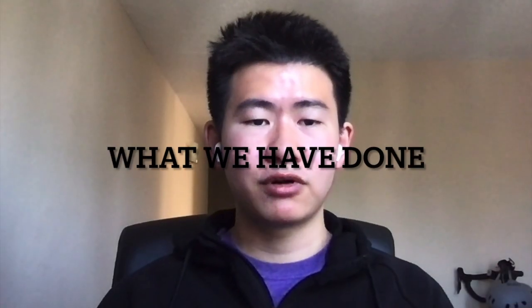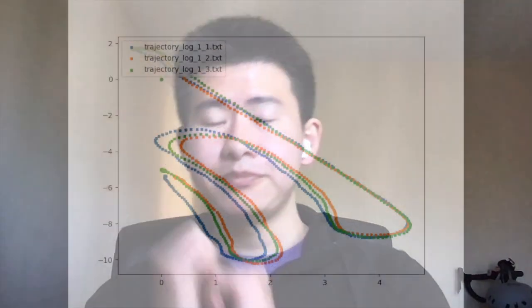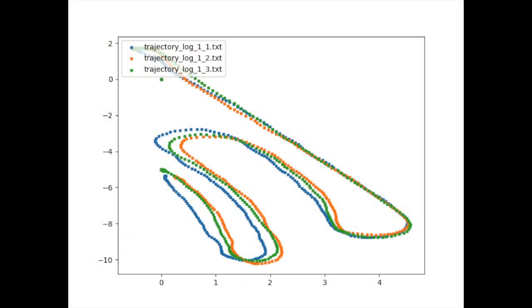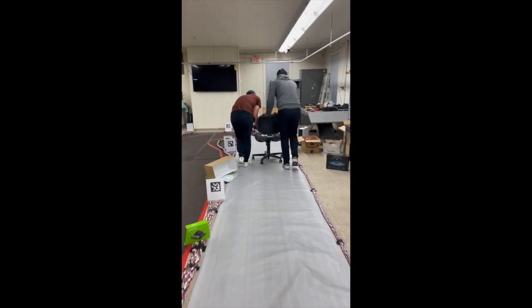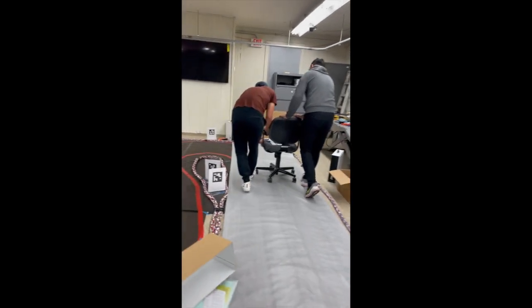We have tested for the hardware accuracies. We have tested the T265 tracking camera in the Richmond Field Station. Localization is one of the most important basic functionalities that any advanced planning modules will require. As you can see in this diagram, the result is pretty good. The three tracks we generated are very close together, and you can see that they belong to the same track. And as you can see in this video, this is exactly how we tested the camera.